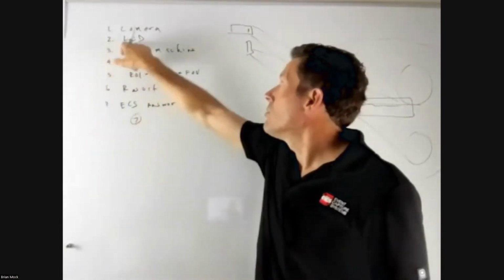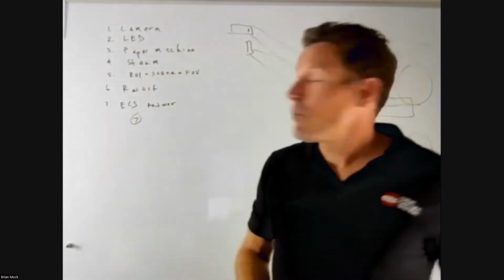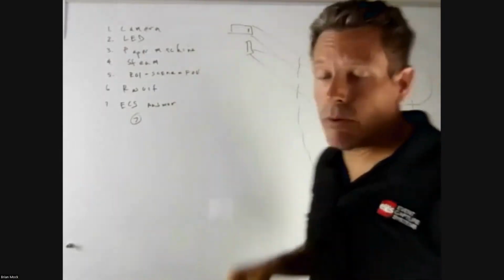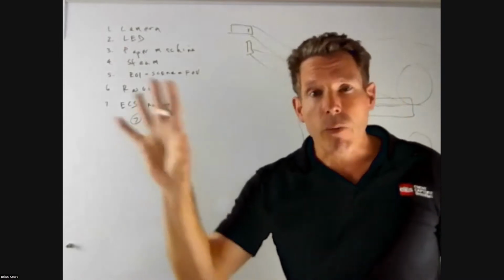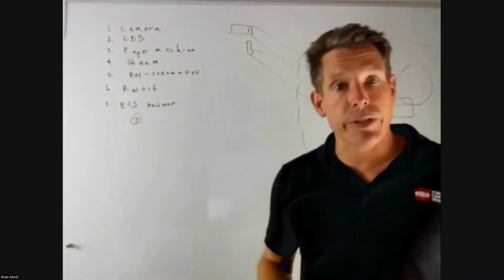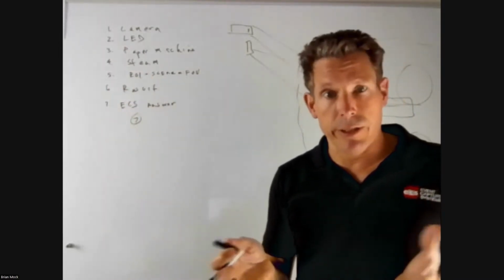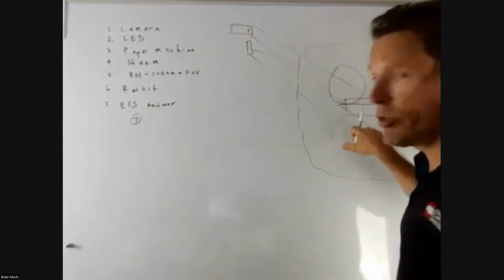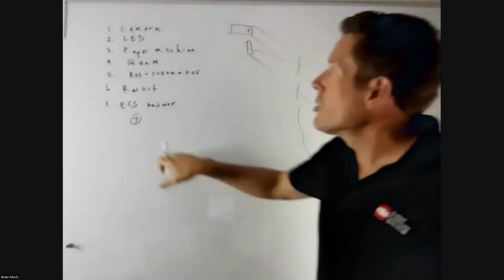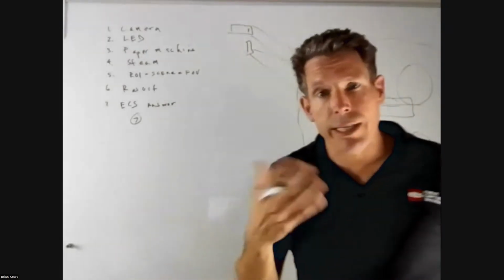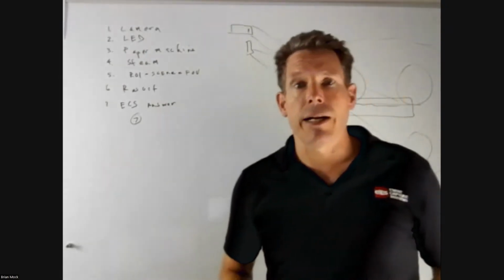So what happens when you use a traditional LED? Well, energy comes out, and the minute it hits that water vapor, it scatters. And it bounces that energy right back to the camera CMOS sensor, presenting it with a wall of white energy. You do not see what's inside of the steam. You do not see the important part of the image. All you see is white steam. So in terms of the ECS answer, number 1 out of the 7, you have to use near NIR.